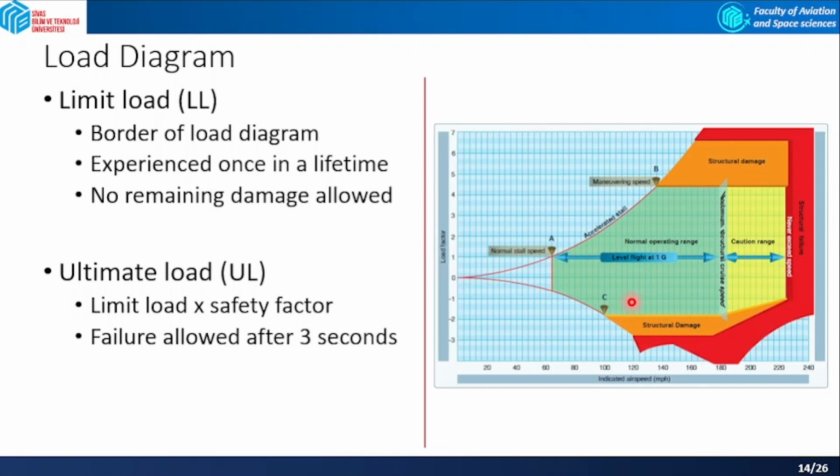The static design of a structure or component is primarily based on the limit load, LL, which represents a high load that occurs only once in the aircraft's lifetime, and all other loads experienced during the aircraft's lifespan are generally lower than this limit load. When the limit load is applied, the structure shouldn't sustain any remaining damage or deformation.